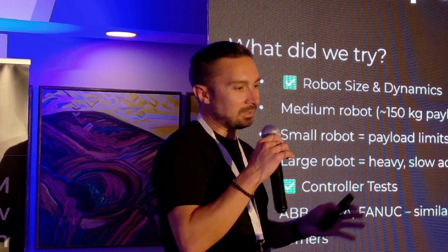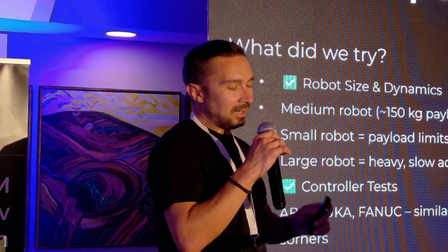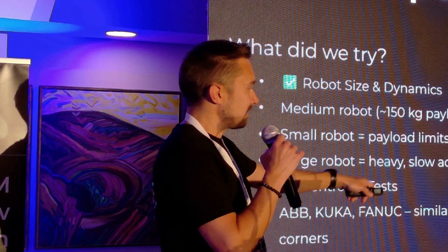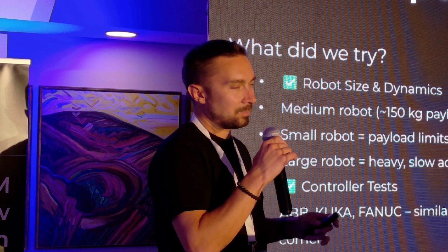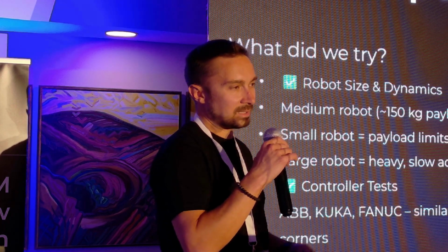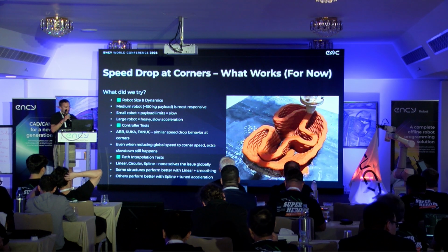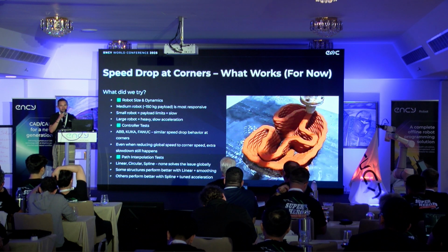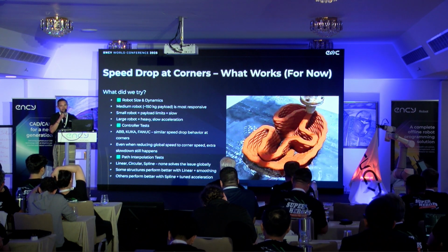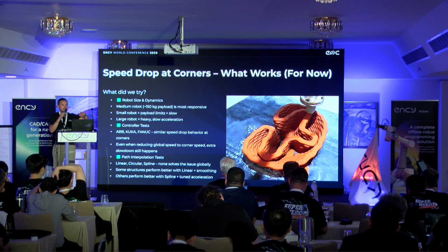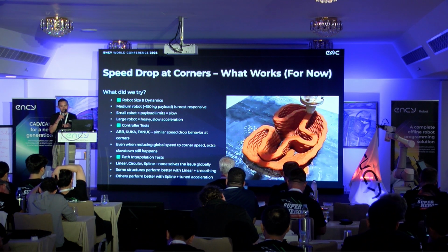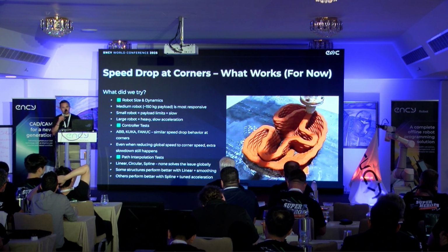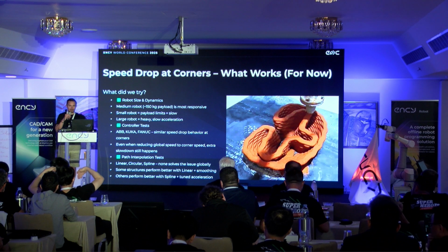For example, we cannot print this one at 300 millimeters per second because it is too fast for robots, and anyway in such a pattern the speed will be less, it goes down, and we need to make some dry run to see and notice what limit of speed we have in such cases, and then using this limit of speed adjust pump speed, because it is important to harmonize the speed of the robot and the speed of the pump.